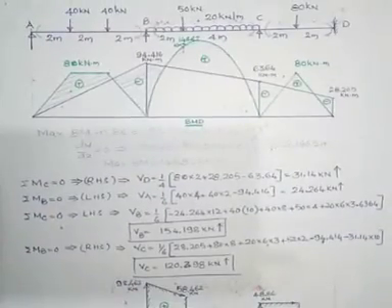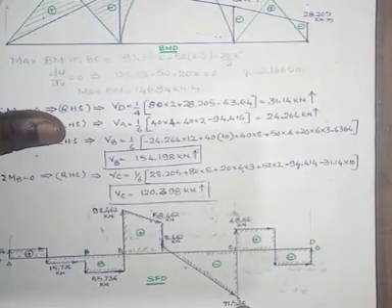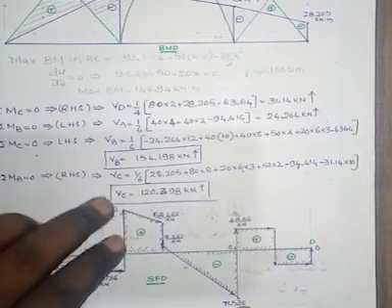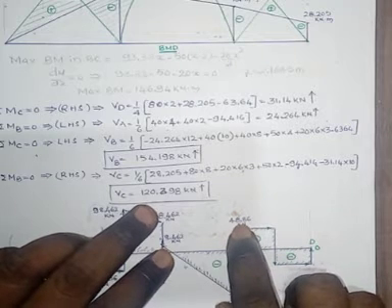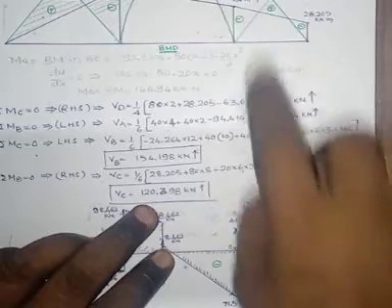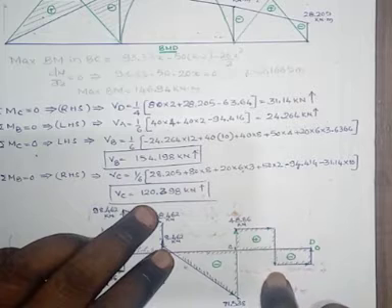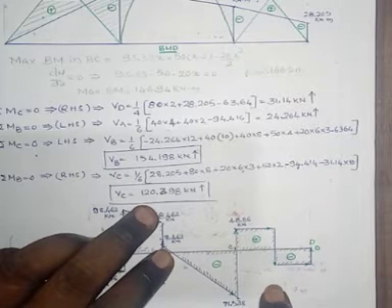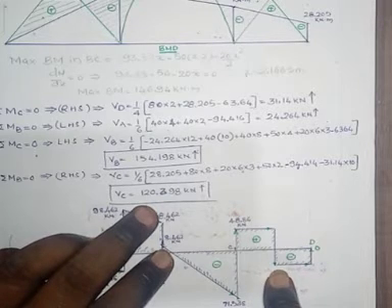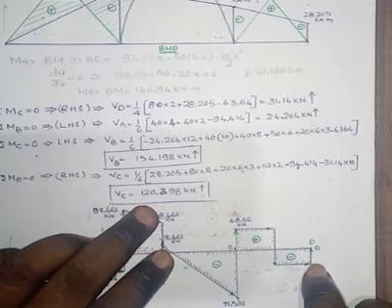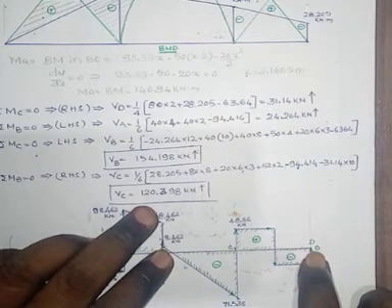71.438. Here this one is 71.438, that is because of the UDL. Then here there is a support reaction VC, that one is 120.398. Then that one is 48.96. It remains constant from C to that point load in between C and D at the center. Then 48.96 minus 80, that one is 31.14 negative. Then it remains constant, 31.14 minus 31.14 plus 31.14, that becomes 0.